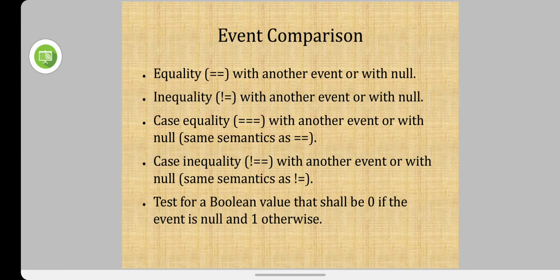Coming to the event comparison, you can use all the equality and case equality operators. So equality with another event or with a null, and inequality with another event or with a null, and you have the case equality with another event or with a null, and the case inequality with another event or the null operator, and a test for a boolean value that shall be 0 if the event is null and 1 otherwise.